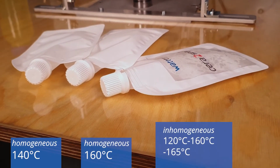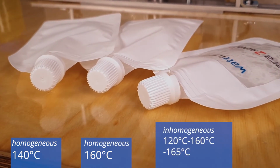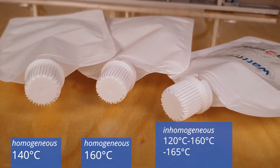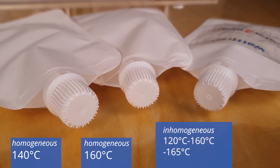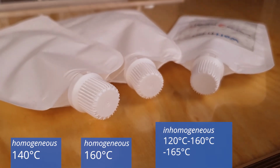So, in a comparison, you can see here again the results. I will summarize this. If you have a low temperature with a homogeneously heated sealing system, a current heated system, then you have a good optical appearance but no good tightness in the spout area.